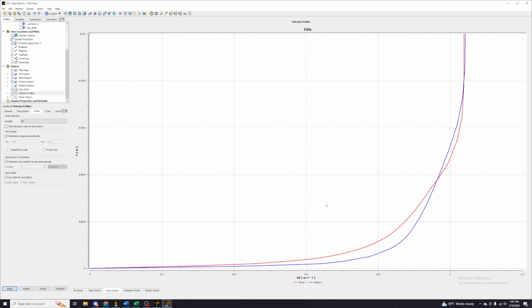You can export all these values, and then knowing that the boundary layer is approximately 0.99 of the free stream velocity, you can figure out where the boundary layer thickness is for the midpoint and the endpoint. It's probably about around here or so, but by exporting it and doing those simple calculations, you can figure out approximately where the boundary layer thickness lies.